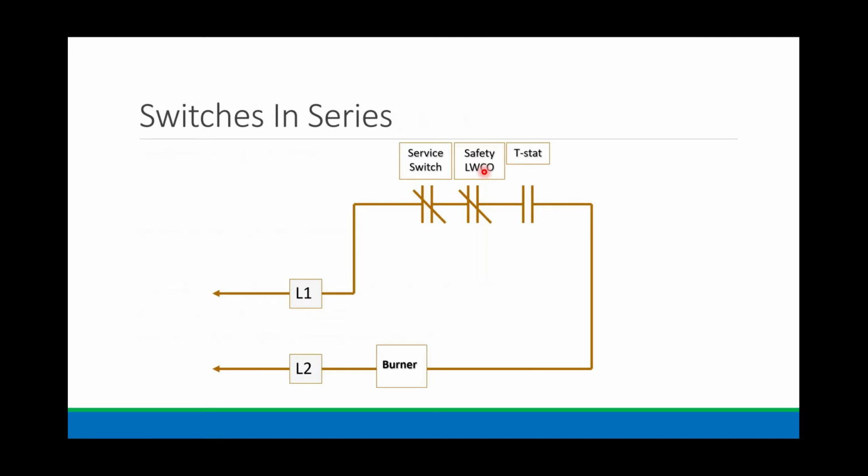So here's my system, and the dark drawn line with the arrowhead, that signifies line voltage, and it's labeled L1, L2. So there's my power. Next I need a switch. Well, I have a service switch, so let's think of that as the switch at the top of the stairs before you go into the basement, and that's in a normally closed position.